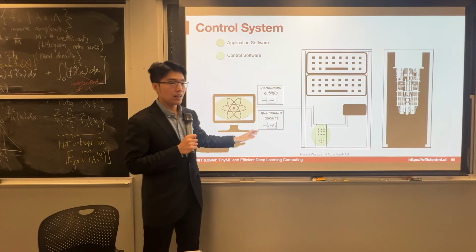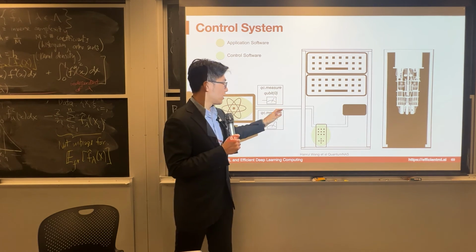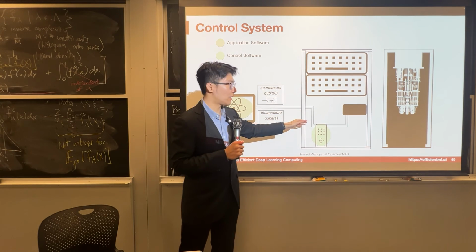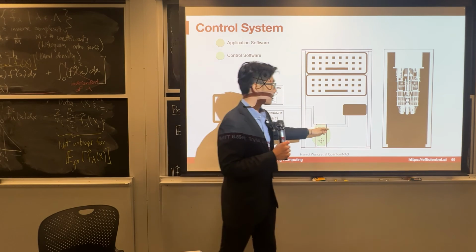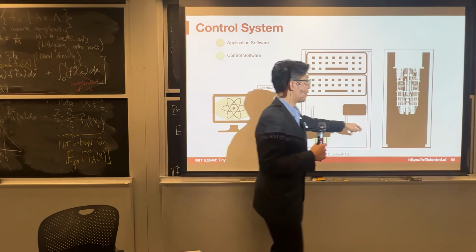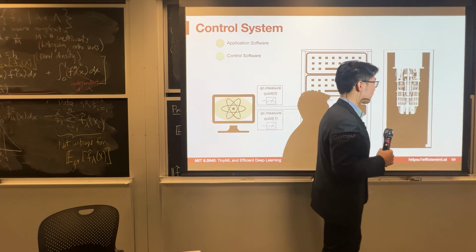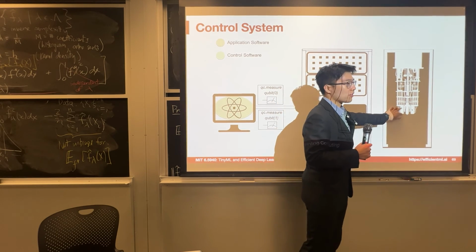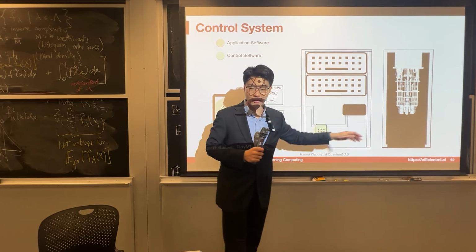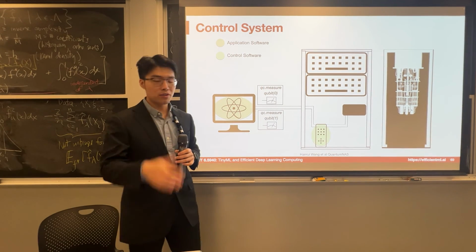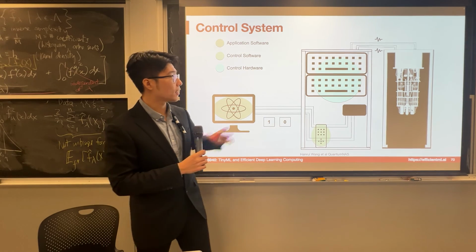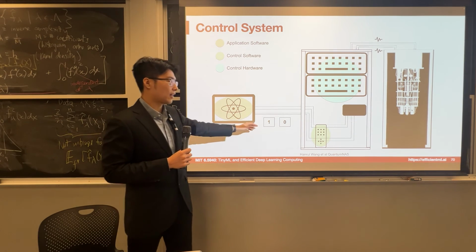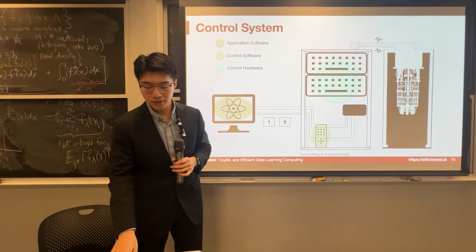After this construction, the circuit is compiled and then sent to the classical server to do the hardware signal generation, and then we send this signal all the way down to the quantum machine. This is called a dilution refrigerator. That means you can have a really low temperature, 4 millikelvin, down at the chip. We send the signal down to the chip, and then we can obtain the measurement outcome from the qubits and send it all the way back across the stack, and then we obtain the classical 0 and 1 from the system, right?